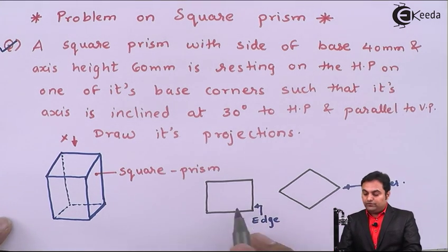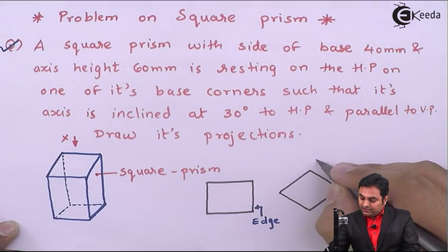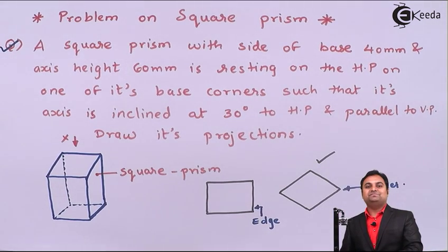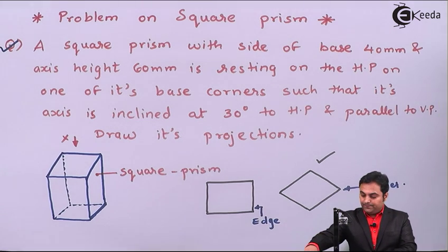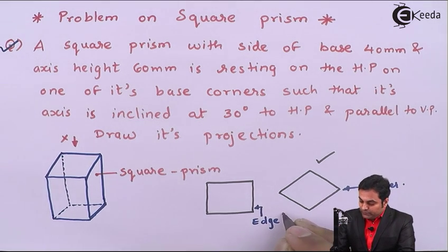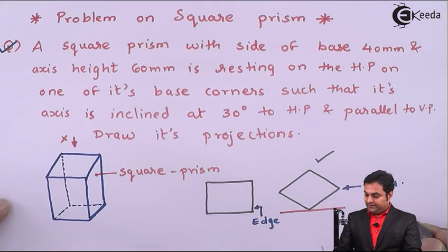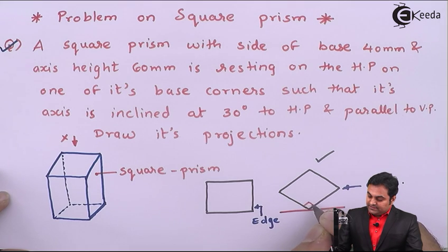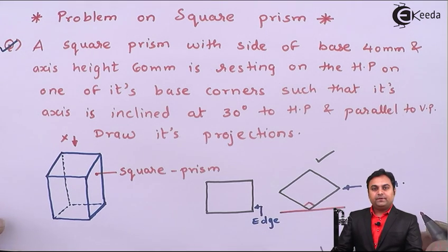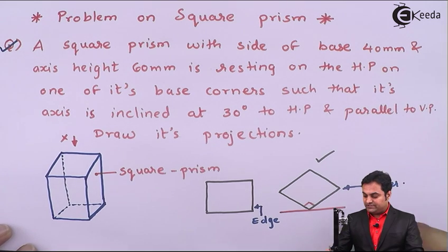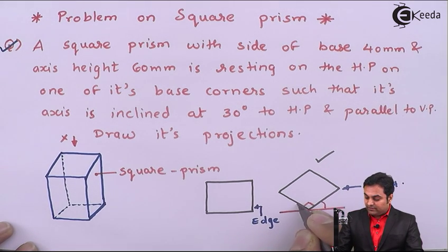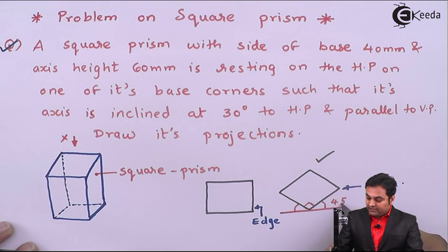It means out of the two conditions, this condition is correct and we have to follow this. Now, how to draw this square? This square, which is the square prism and looking like a square from the top view, since it has this angle as 90 between the edges, or we can say between the rectangular faces, so the remaining angles are 45 degree on each side.